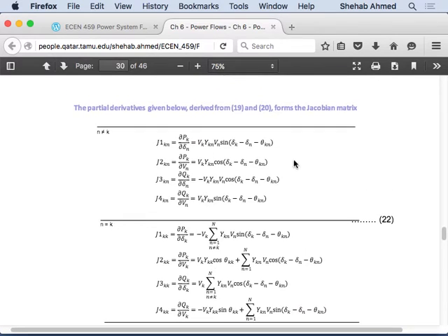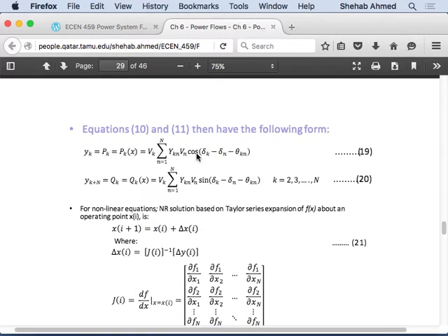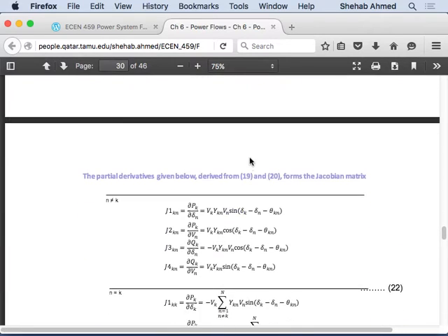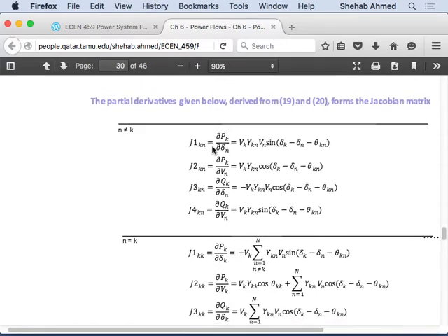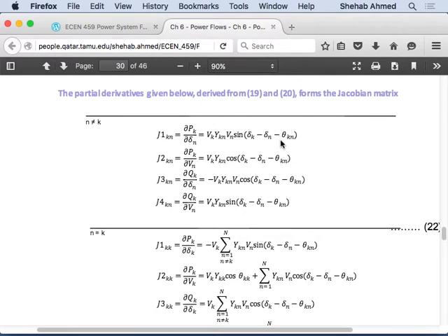The equation for dP by d delta is fixed, because I just have a single equation that I'm differentiating. But the elements of that equation contain the v and delta, so the value of that differential will change every time in the Jacobian matrix, because every time you're plugging in a new v and a new angle. Does it make sense?